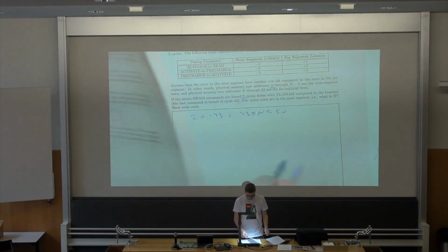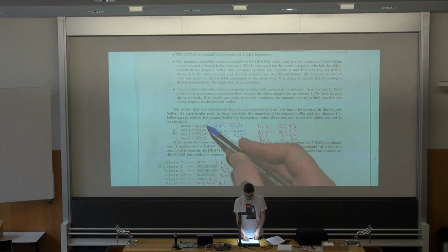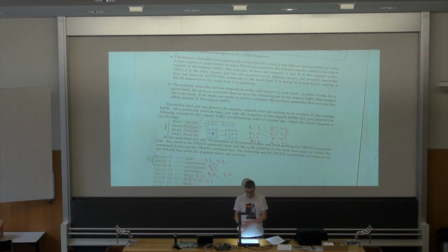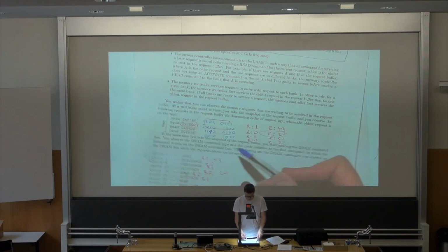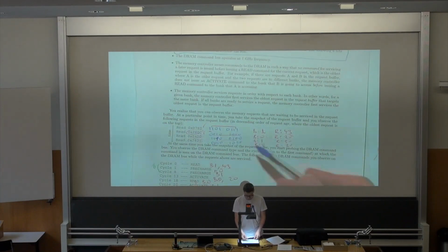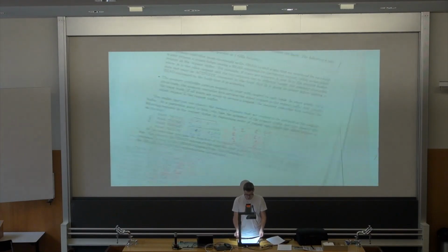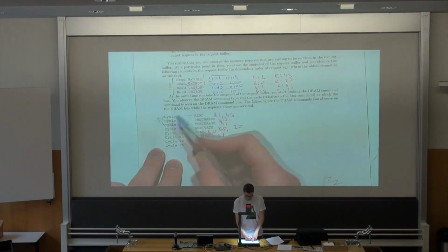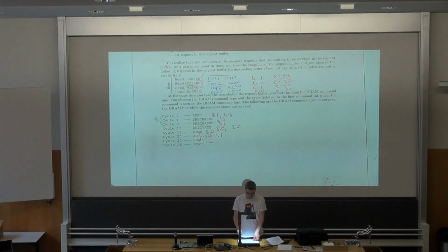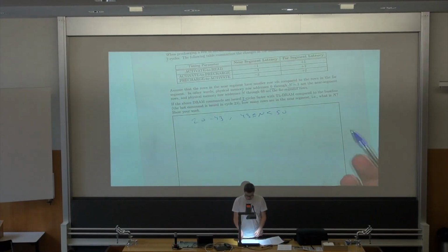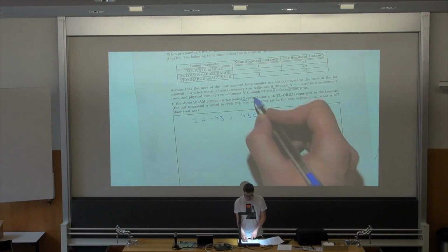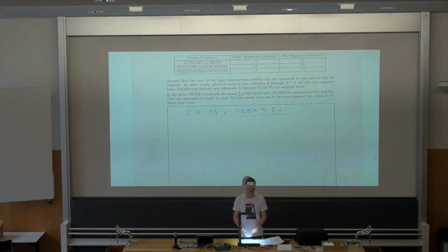redo what will happen to how those requests will be serviced, because you know everything you need to know to run the simulation, right? So you know the initial state, you know the requests, which banks and which rows they target, and based on that you can simulate a new command trace here. And once you do that, you will see that this works fine, and it gives you exactly 2 cycles of latency saving.